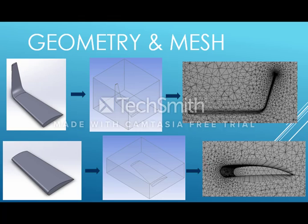The mesh for the wing with the winglet was created using the curvature size function and a medium relevance center. 5 inflation layers were also added to help capture flow around the airfoil better. Due to the element limit in the student version, a finer mesh could not be made for the wing with the winglet. The mesh for just the wing was also created with the curvature size function. A fine relevance angle was used and 10 inflation layers were added.